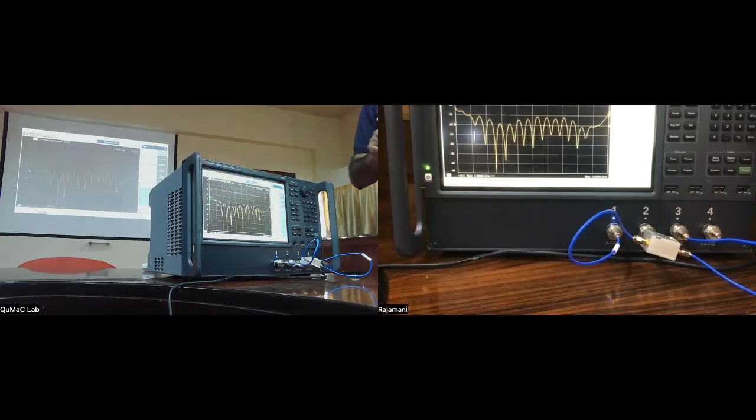Like there's actually a resistor inside the device, which will absorb power when used in this direction. Okay, but there's something subtle to it. I'll mention it in just a second, but I will not go into the explanation of that. So this is again a characteristic feature of this kind of device. The fact that no power goes between the two outputs means that this is isolated. Again, in the ideal sense, it's mostly isolated, very low power. So port 1 and port 2 are isolated in this manner.